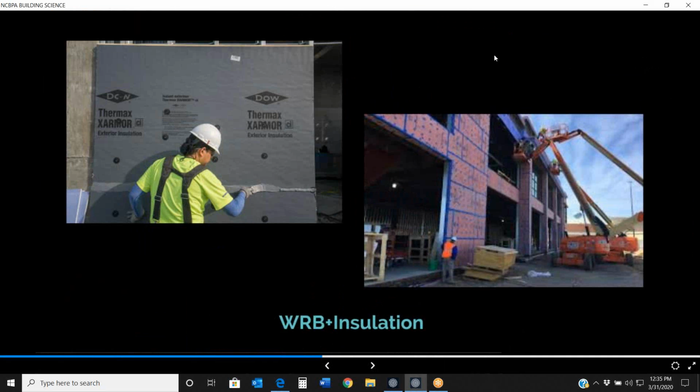If we're installing a vapor closed or a low permeance system on our walls, we need to understand what happens with our vapor control. How is that being managed inside of the building? Are we having to take second steps to mitigate any of those risks with these systems? But all in all, they do handle a lot. I think they're impressive. They come at a high price point, but they're handling a lot of our control layers.